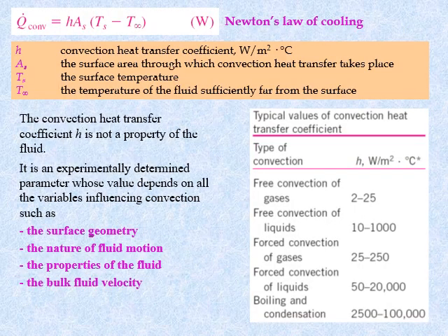Okay, convection follows Newton's law of cooling, which by this equation is proportional to A and the temperature of the surface of the solid body or any body that has high temperature minus T infinity, which is the surrounding temperature. And h here is the convection coefficient. So A is the surface area. We can see here h is the convection heat transfer coefficient. This value h depends on the condition, depends on the environment, and depends on the velocity. So in the next chapter, you will need to know how to calculate the h value.